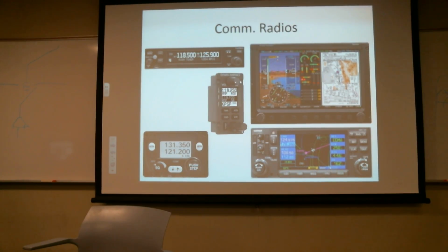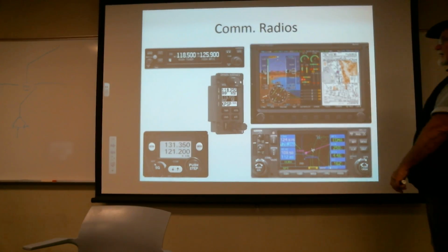Now, if you only have a single radio, this is kind of handy. Pulling out from between the hangars, I flip on the ATIS, listening to ATIS. Meanwhile, I've tuned in the ground frequency. Okay, get ready to talk to ground, pop the button, ground's now active, tune in tower frequency. Talk to ground, tell them I don't like them, but where I want to go, and then change my attitude and say I'm going to buy them chocolate. They give me permission to go. I go up and do my run up, pop the frequency again. Now tower is active. Tune in my in-flight or maybe TRACON or whoever else, or if I'm flying formation, whatever discrete frequency it is, I can keep popping along.